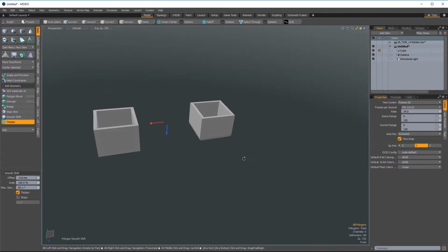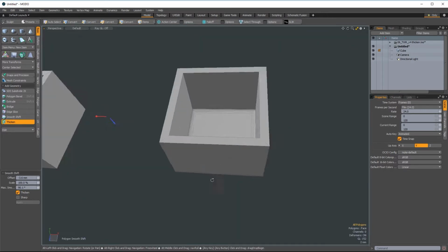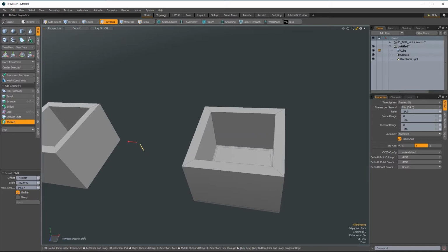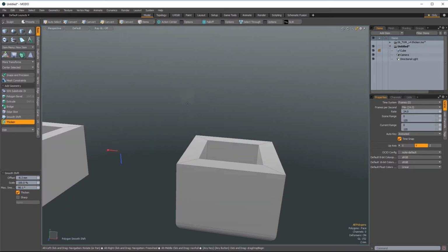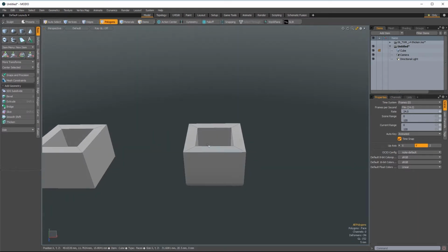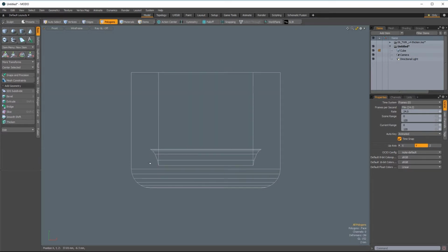Be careful though, if you look at this box on this side, which has these filleted edges, you can only thicken on the inside so much before you start creating intersecting geo, which quickly becomes problematic. So I'll pop into a wireframe mode here just so you can see what has happened. So this geometry is completely inverted and is now intersecting.